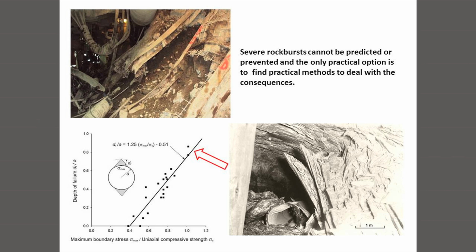Brittle materials like concrete or shotcrete don't work in these circumstances because they are simply too stiff and too brittle. So they will not accommodate the movement. And finally, we come to the rock burst problem, where you're now very deep, you might be 2 or 3 kilometers underground, and where the rock is failing violently.